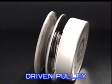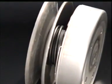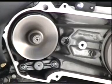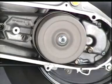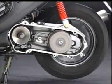The driven pulley is generally pushed by a spring in the direction in which the pulley width is narrow. When the diameter of the belt on the drive pulley side is increased, however, because the belt length is constant, the spring of the driven pulley is defeated by the drive pulley force, and the driven pulley diameter becomes smaller. At this point, the power being transmitted from the engine by the belt is conveyed from the clutch drum to the drive shaft by the centrifugal clutch built into the driven pulley.